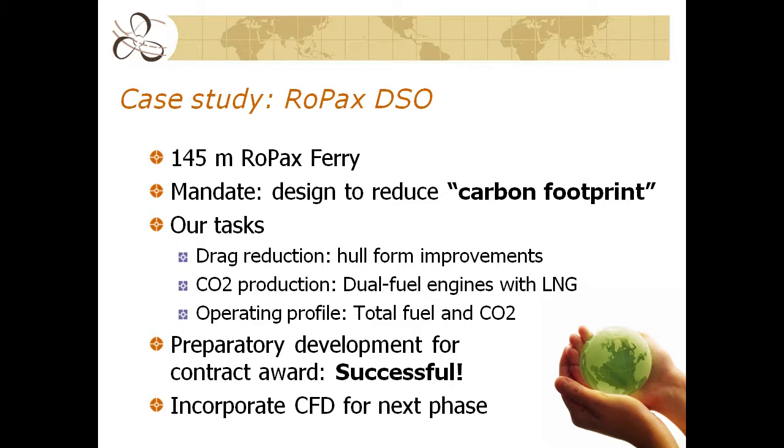It was very nebulous, which, for designers, that's great because it allows us to actually think and try to be creative about things. But our tasks in this were to look for drag reductions, first be able to do the prediction of the drag, look for drag reduction opportunities, to do a prediction of CO2 production, because that's going to be the benchmark on this when they're talking about a carbon footprint. That means CO2 production. And we were to look at this with dual fuel engines with LNG as an option, and to assess this across an entire operating profile where we're looking at total fuel consumption and total CO2 production across the entire voyage.